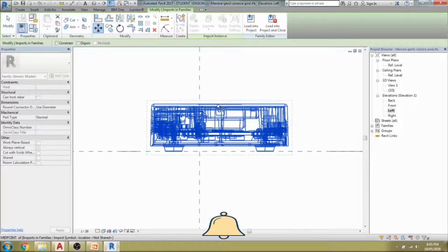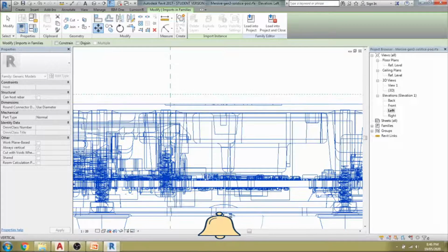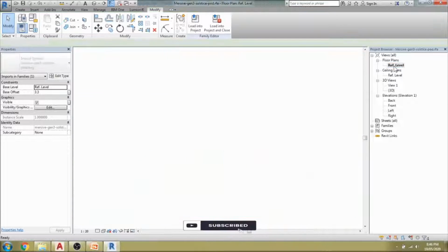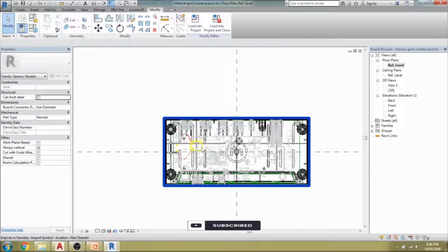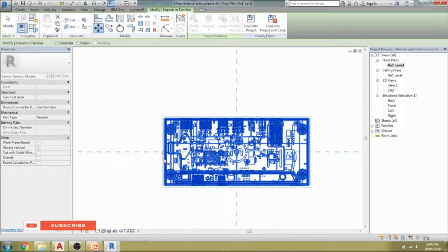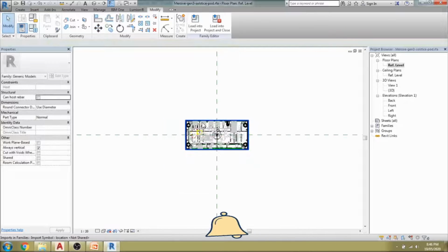There are many lines, so you have to use the proper midline and stretch it back to the center axis. Going back to the reference line in the floor plan, we have to do the other side also. Move, snap to mid. Both sides are already aligned, so it's perfect now.